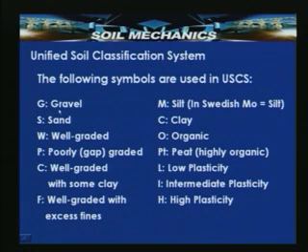G indicates gravel, S indicates sand, W indicates well graded, P poorly graded or gap graded, where some of the particle sizes are absent. C is well graded with some clay, F is well graded with excess fines.